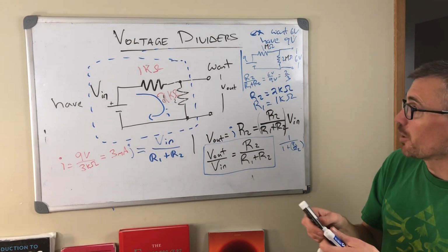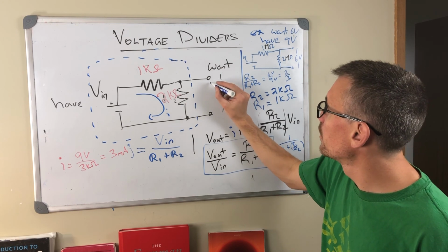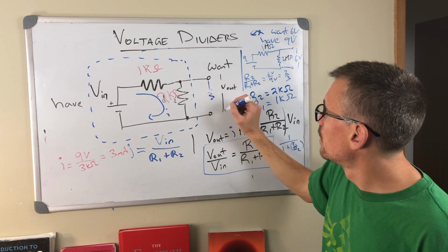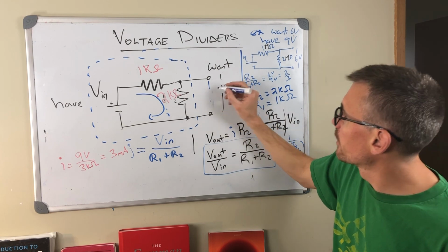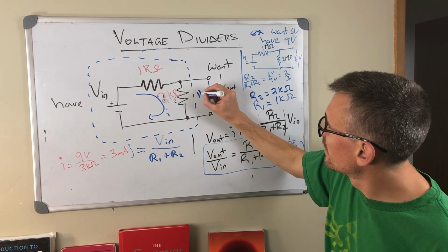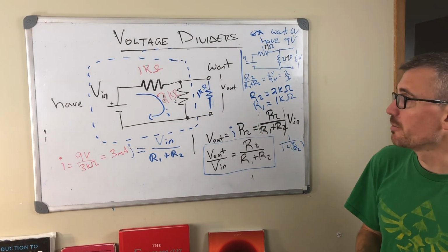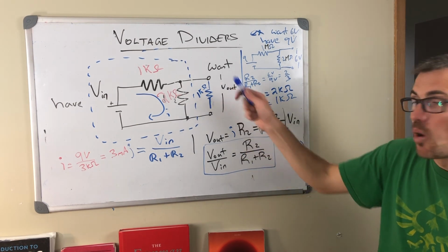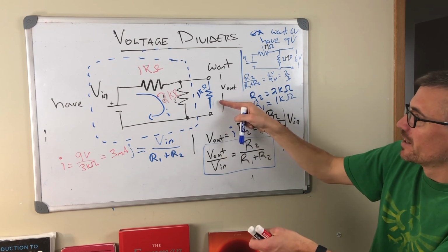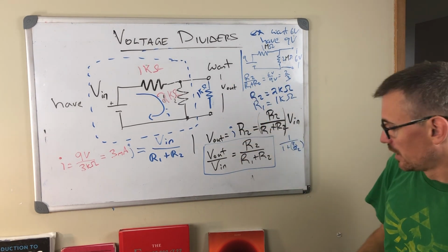But what I'm going to do is plug it into a 1 kilo ohm, or let's say a 2 kilo ohm load. Doesn't really matter what it is. I don't know. Let's make it 1 kilo ohm. Let's make my math slightly more cumbersome. A 1 kilo ohm load here, and I'm going to measure my 6 volts, right? In fact, when I plug this in, I'll measure it. 6 volts, great. I'll plug it in, and it won't turn on because all of a sudden I'll have much less than 6 volts here.